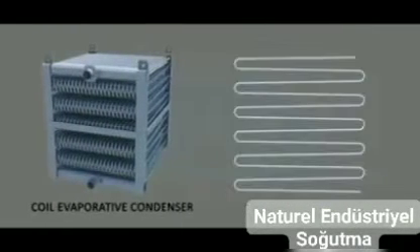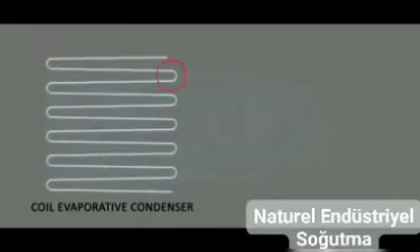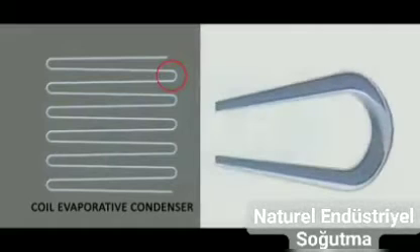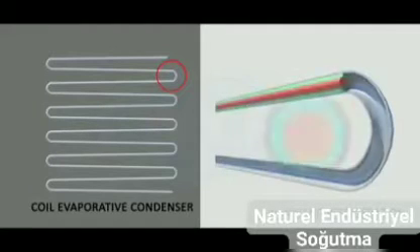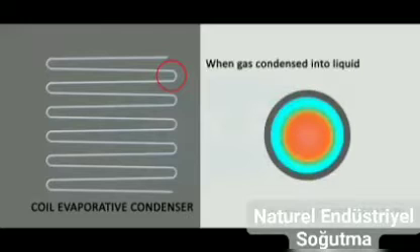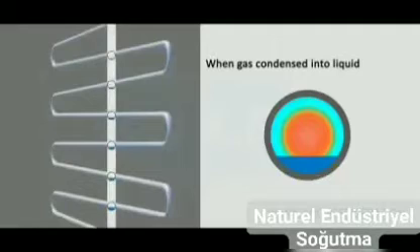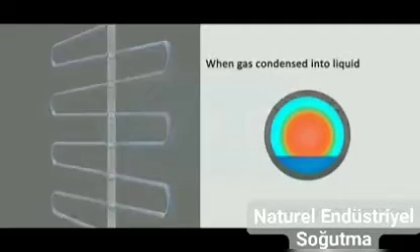In the case of conventional tubular coil evaporative condensers, the cross-sectional area available for the hot entering gas is relatively larger. This results in lower gas velocity, which is unable to maintain a uniform annular film along the tube periphery, and therefore very early along the flow path, a separated flow is formed with condensed liquid occupying the lower section of each tube, and therefore results in lower overall thermal performance.